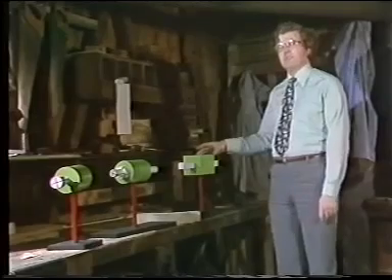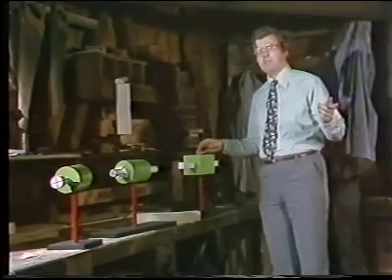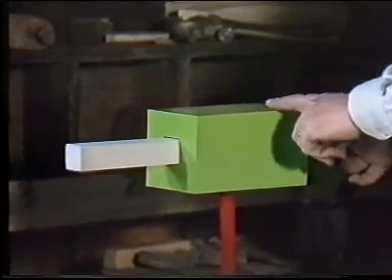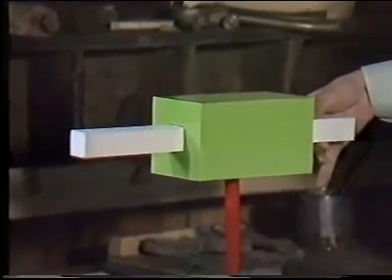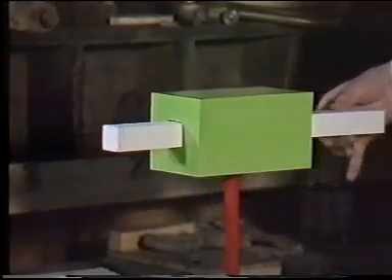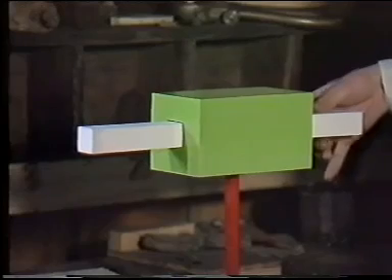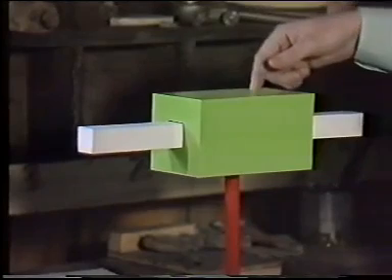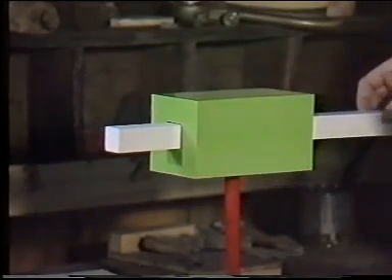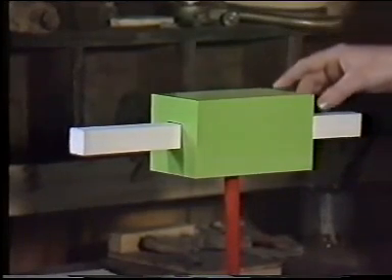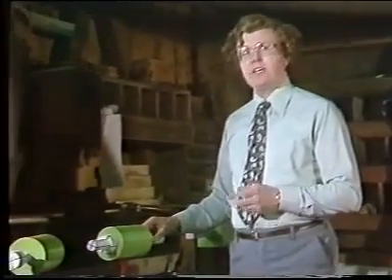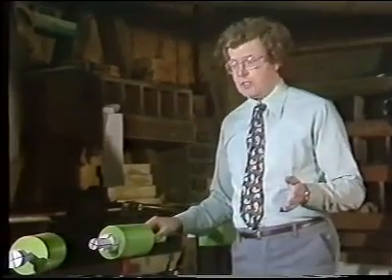And the first one is of the prismatic pair that you saw out on the engine. And you can see from the model this allows a sliding motion, a translation, but I can't turn it at all. So there's only one way in which I can move one link relative to the other. And that means that if I want to specify the position of one link relative to the other, I only need one parameter, the amount it's moved. And so we say that this joint has 1 degree of freedom. Now the next joint is the revolute pair, and again you saw this out on the engine.